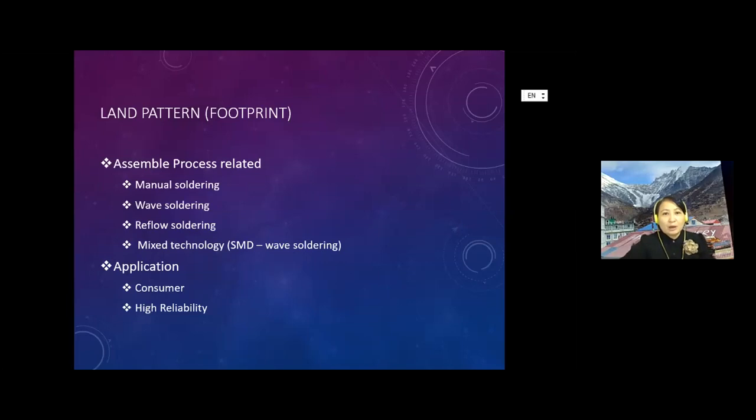So we will see that almost 70% will actually create the footprint. So I guess you would need to be aware that the datasheet footprint size is kind of generic, and if you have anything specific, or maybe you're doing a high reliability kind of product, you need to be careful with that. Okay, so the majority of components are SMD. This is pretty expected. And you have probably through hole here.